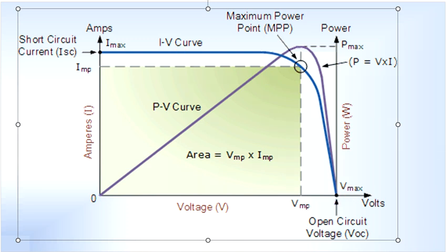So for this IV curve, if you take the product of I into V and plot it versus V, you will get this plot, which is nothing but the P-V curve. So are you getting it? P is nothing but I into V. If you take the product of I into V at a particular voltage, that versus the same voltage will give this plot. This is coming because of the variation in current after a certain voltage. So after this particular voltage, what's happening? The current is going to be reduced as we increase the voltage across the solar panel.